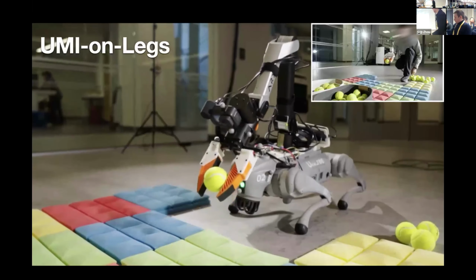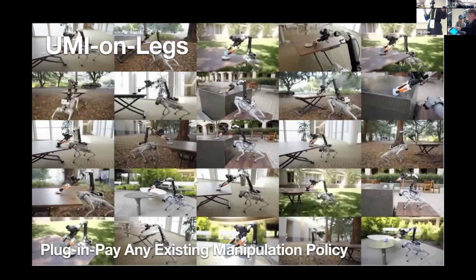And then I think what's more exciting is that once you have this system, you can directly plug in the original UMI policy that we trained for the cup rearrangement task into this legged robot, and it immediately worked zero-shot on a new, different robot embodiment. So that means we can completely reuse the data that we collected in the earlier project. For this project, we directly used the policy that we trained on UMI. We didn't do any fine-tuning, and didn't do any data collection.